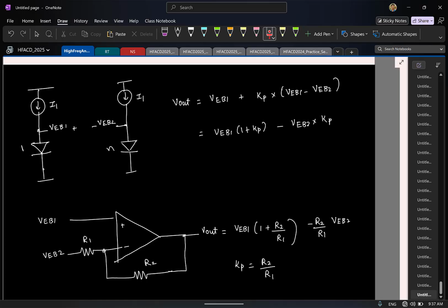The ratio of two resistors. So if you make both resistors using similar kinds of elements, with temperature change, let us say R2 becomes R2 times (1 plus delta). What do you think will happen to R1? That will also change by the same factor, so the ratio will be constant.